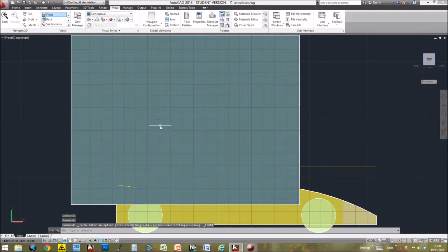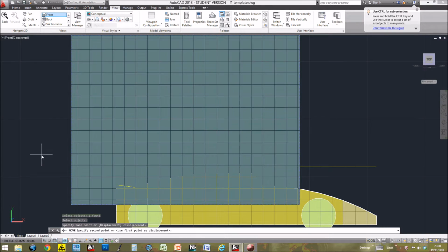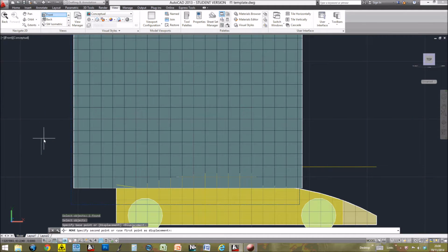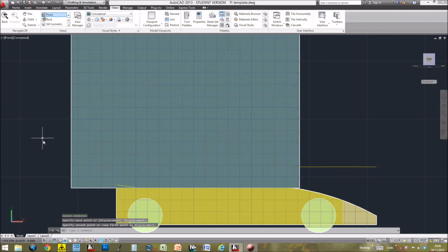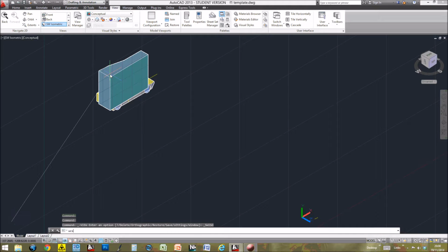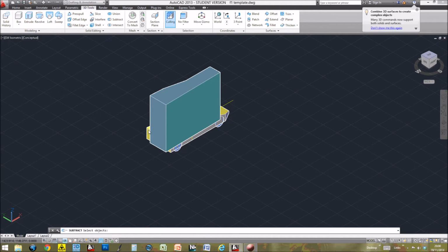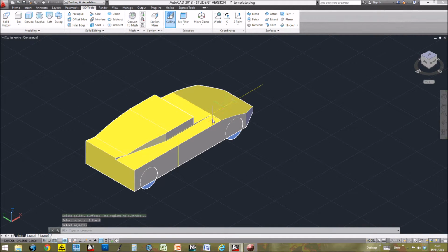And we can now see where we want this to work. So let's move this again, bring it up, and we can see if I bring it to here, it's going to chop across the top there and cut around the side, which will work better. So let's go back into my 3D view, and we can see it here. Change my UCS to world. Just check how this is going to look, so we can actually use this to design and model as we're going along. 3D tools, subtract. Take my object, subtract that from it. And that's looking a little bit better, but we could see actually if I wanted to, I could design this so it cut more out over there.